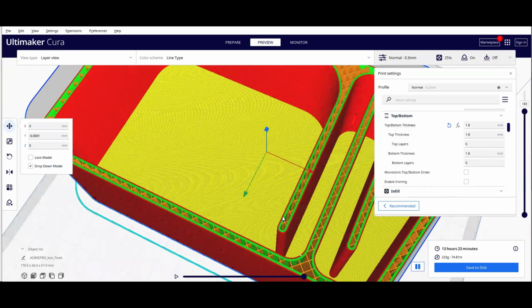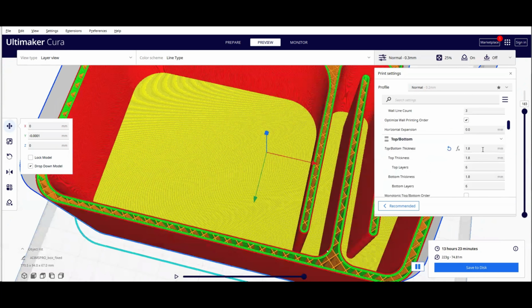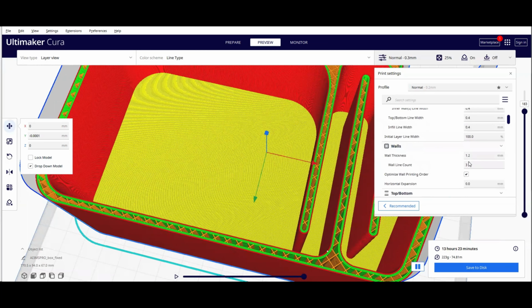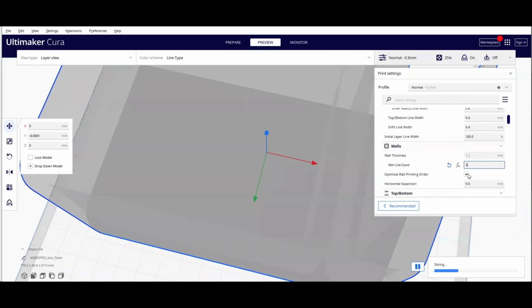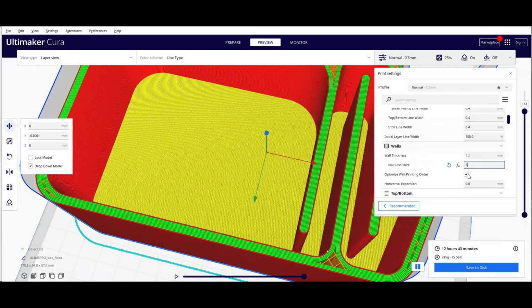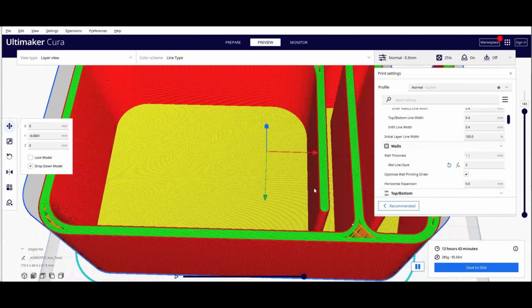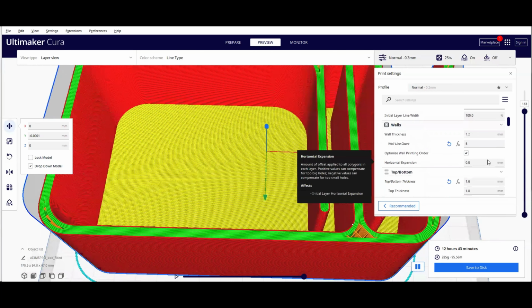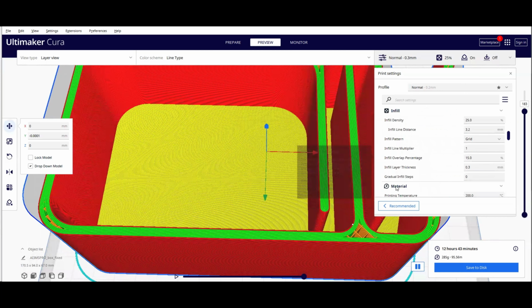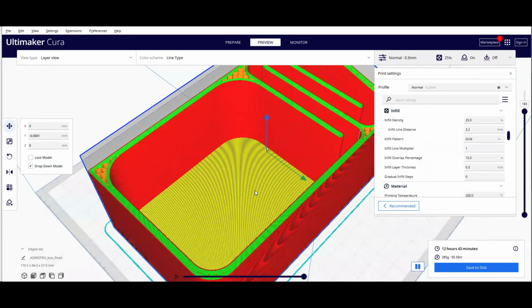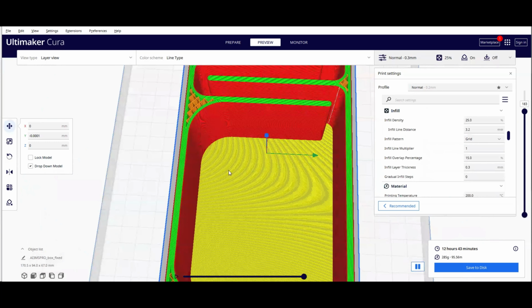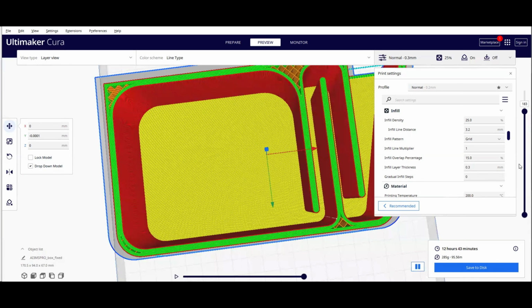So you could see from where I was, if I was to go back to the wall thicknesses back to 6 again or 5, it's actually went to 12 hours, went less. So it's actually better this way. There you go. All right. So I think that's probably the best outcome we're going to do, is make it a solid. Don't have any infills at all right through. This will become a nice solid box.